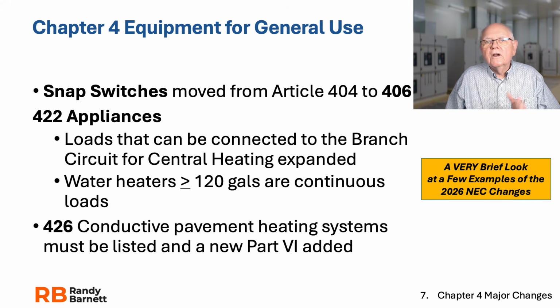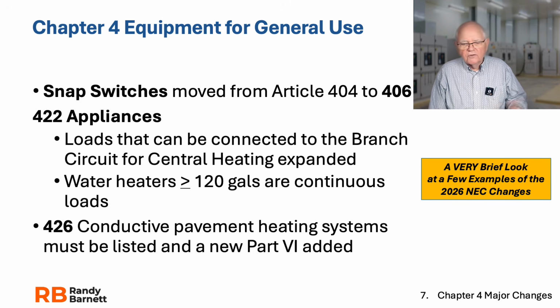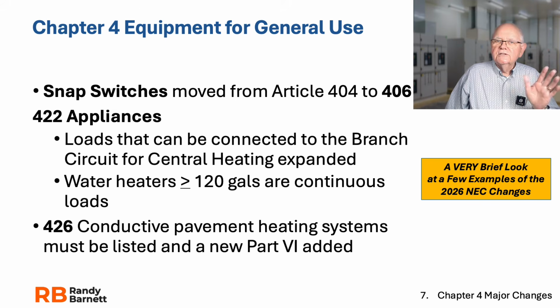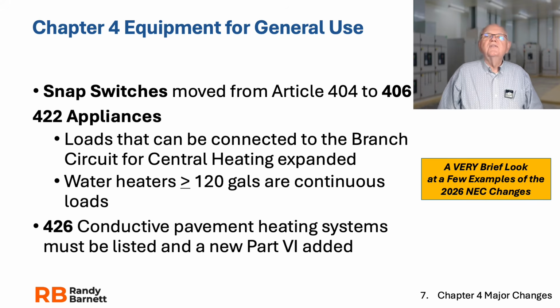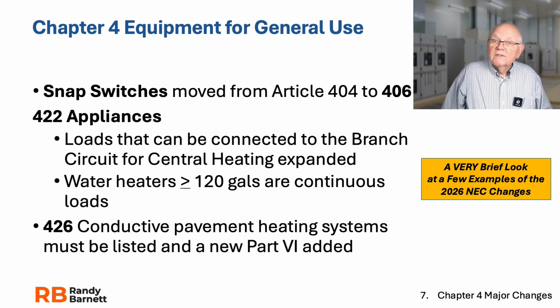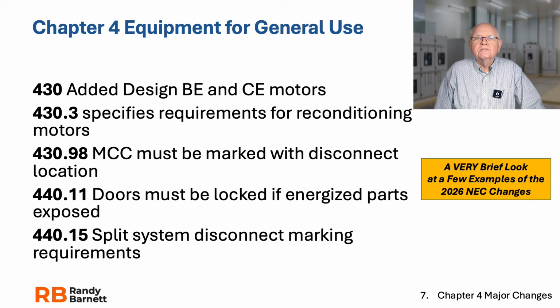So if I have an electric water heater greater than or equal to 120 gallons, it's a continuous load. But yeah, mine cycles off and on and doesn't run for 3 hours straight. Hey, continuous load, all righty? 426, conductive pavement heating systems must be listed. We already saw the new definition for these conductive pavement heating systems, and now there's a new part in Article 426 that has been added to address these conductive pavement heating systems.